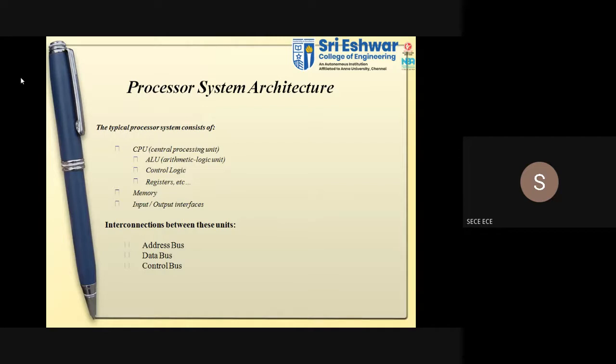So all put together, which is said to be system bus. Address bus carries only the address of the application, the address of the codes. Data is nothing but the data which we are going to use in the programs. For example, if I am going to add two numbers, my instruction will be sum a comma b or 3 comma 4. So 3 comma 4 will be the data, sum is nothing but an instruction. These two will be placed in one particular address in the memory.